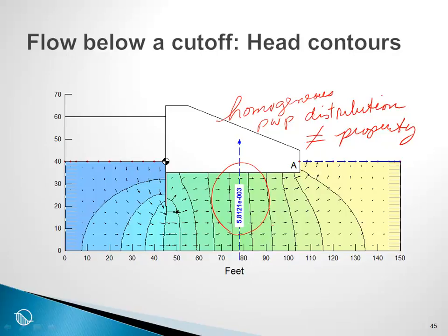If the amount of flux is not all that important and all you are interested in pressure distribution, then any approximate estimate of saturated conductivity is more than adequate. So here's a case, depending on the objective of the analysis, the saturated conductivity may be important, but in some cases not important at all. To repeat, if you want to know the flux, big Q that goes through this section, then of course it is directly related to your accuracy in the definition of the saturated hydraulic conductivity.